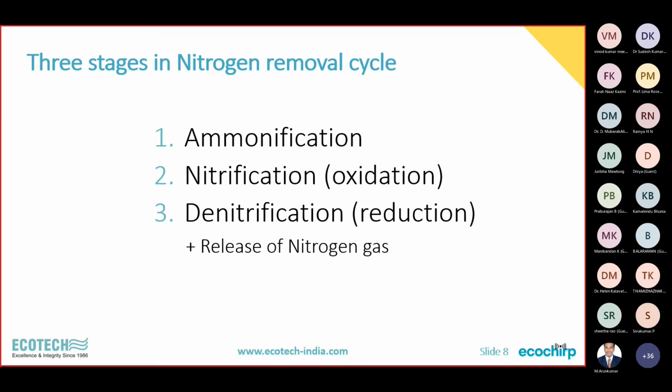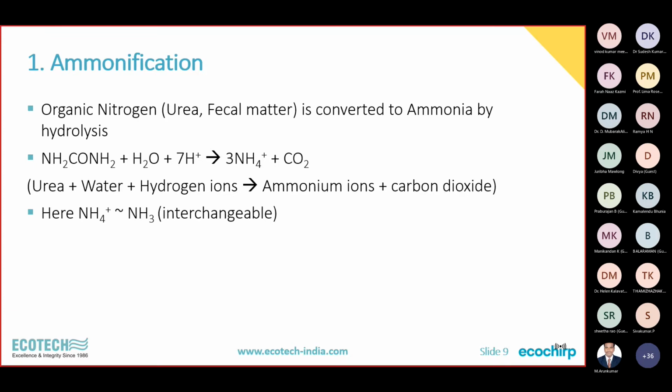So you have to be aware of all these differences which you can encounter in the raw sewage. So as a thumb rule, yes, for domestic sewage it says 25 to 30, but you have to take it with a pinch of salt, apply your common sense and some logic, and see whether it applies at the commercial scale. It may be totally different. In fact, we have witnessed this in one of our treatment plants. It went as high as 60 milligram per liter, and therefore we had to do a special study to see how to control the nitrogen to less than 10 ppm. So we have to be careful. We have to characterize the wastewater extremely well before we apply any of these denitrification strategies.